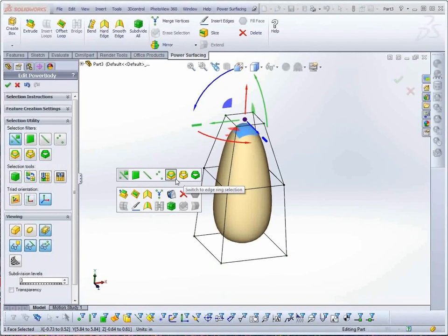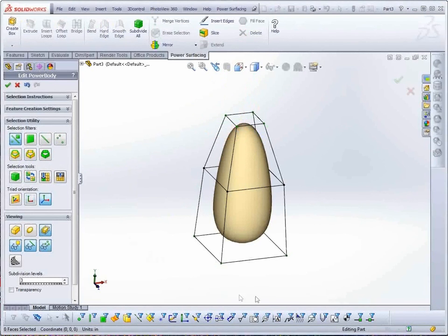Or, if you are still in Select Any mode, you can double-click near the center of an edge to select an edge ring. In Select Any or Edge Selection mode, double-clicking in the center of an edge selects an edge ring, while double-clicking near a vertex selects an edge loop. With faces, the edge you select nearest determines which direction a face loop will be selected.